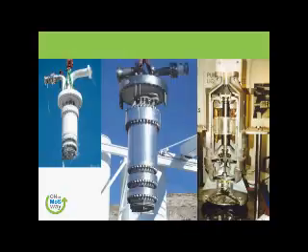Okay, let's press on. This is where the liquid will go. The partial liquid will also go and do the cooling of bearings. Technically, there are no lubricants or grease here, because no grease will sustain minus 161 degree temperature. It will freeze. So normally we are using the cargo itself as a lubricant, as a bearing.